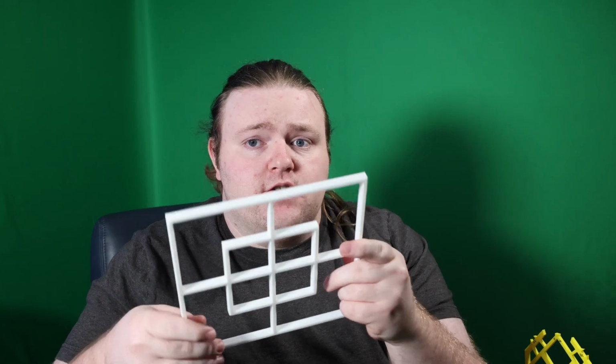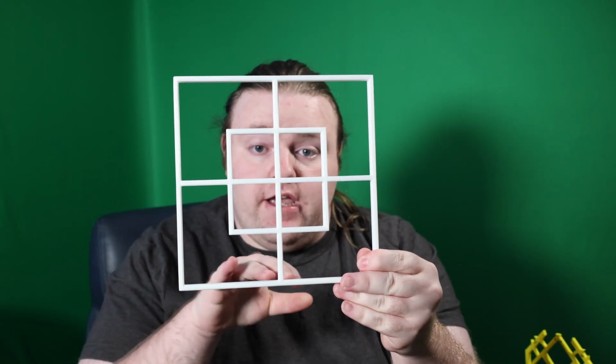Namely, the first thing is the video almost entirely talks about skew in the XY plane, which would be like the print bed itself, this way. But there's actually two more planes. There's this plane, which on my printer is the X and Z plane. And then there's this plane, which is the Y and Z plane. And the printer can be skewed in any one or all of those planes.